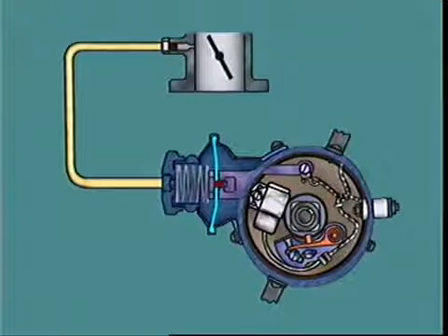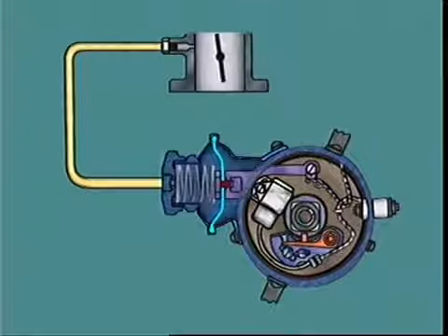As the throttle is opened wider, there is less vacuum effect in the manifold and consequently less vacuum advance. At wide open throttle openings, there will be no vacuum advance at all, and ignition advance will be determined solely by the speed-sensitive mechanism.